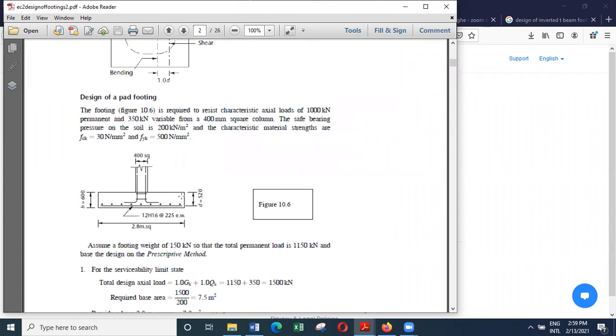Unless you suspect that the amount of concrete involved is too much, that there can be some kind of thermal cracking. There's a possibility for thermal cracking that occurs only in very heavily loaded large column bases having a greater thickness. Then you can provide some nominal reinforcement here. Otherwise, no need to provide any top reinforcement.